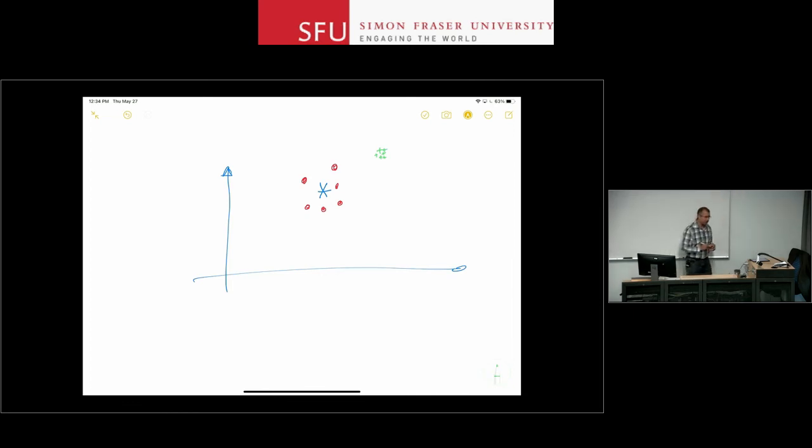Accuracy is about how close the values are to the true value. So between these two sensors, well, this one is giving me a more accurate reading, right? The red one or the circular ones, because they are closer to the true value. But the second sensor, the one that produced this group of values, is more precise. The readings from that sensor are tighter, are closer to each other. So even though it is not as accurate as the first one, it is giving me a more repeatable output, reliable in terms of repeatability.